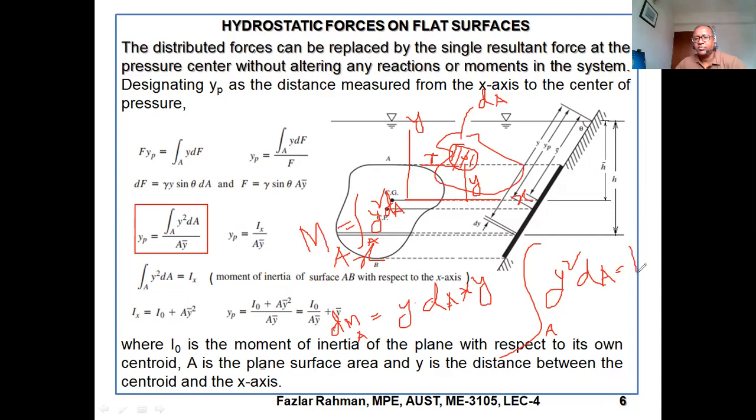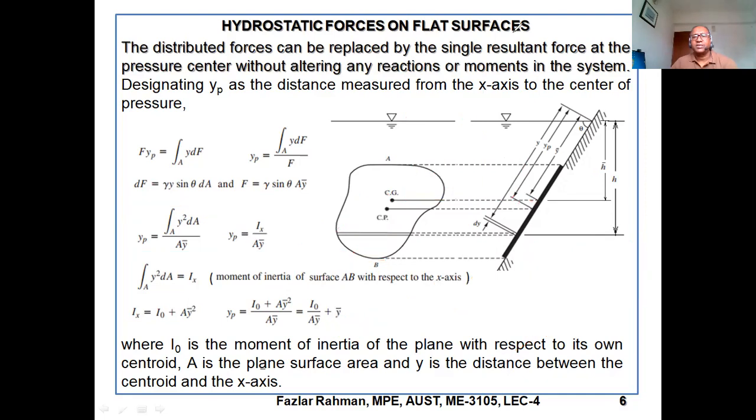That means ultimately you are getting the moment of inertia along the x-axis, because the distance from the x-axis is y. So Ix. Do you remember this equation? In engineering mechanics, look in your class notes: Ixx equals integral of y square dA, and Iyy equals integral of x square dA.